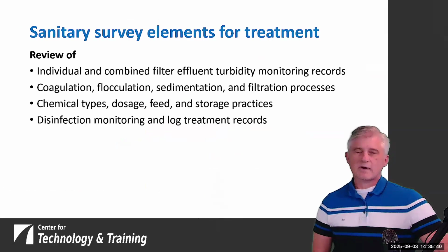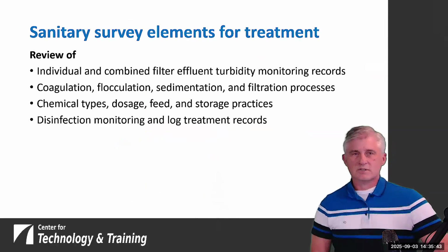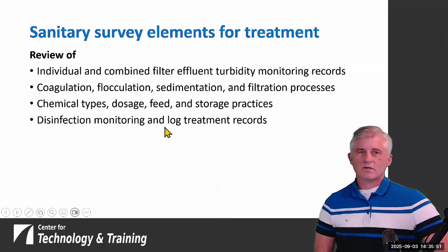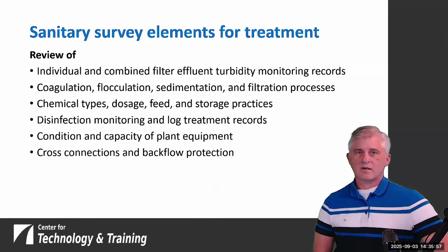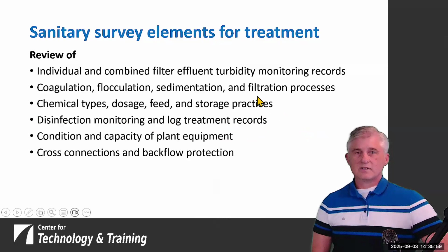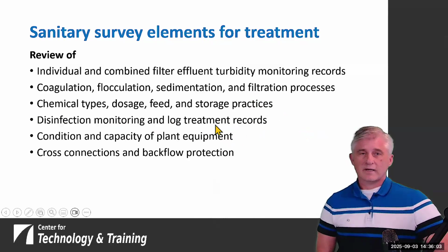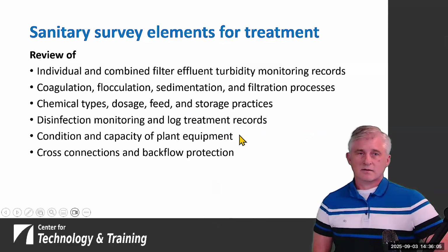They'll look at the chemicals you add, what your dosage is, how you feed them, how you store your chemicals, what your disinfection monitoring looks like, and your log treatment records. How are those records comparing to what you're supposed to be having? What's the condition and the capacity of your plant? Are you able to provide the proper quality of water?